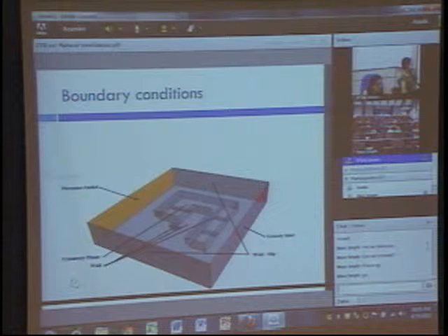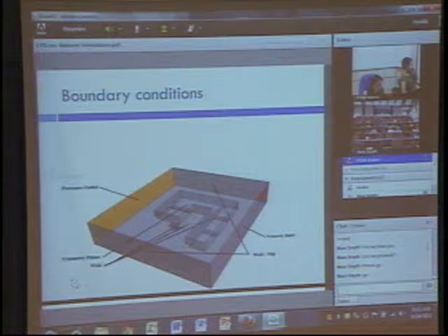When we have considered the geometries that we're going to model, the next step is to define boundary conditions. Boundary conditions are numerical constraints that the model requires to compute. We need to have velocity inlets, pressure outlets, and all the wall and roughness definition in order to consider the movement of air. It depends on the characteristics of the geometry. We can make some sort of symmetry in order to save cells.